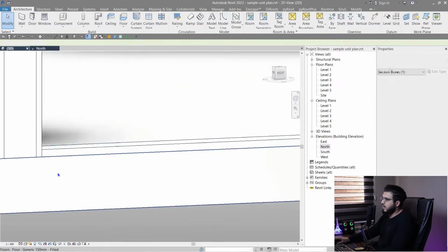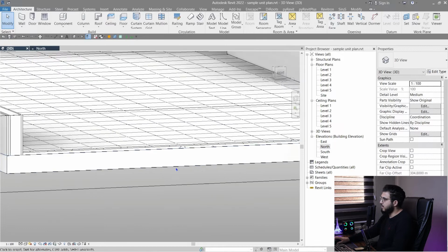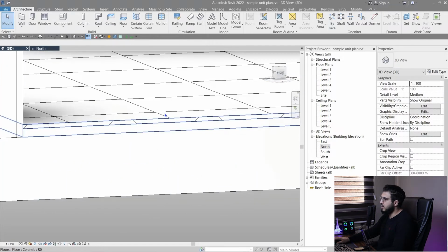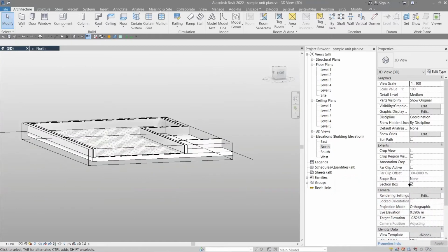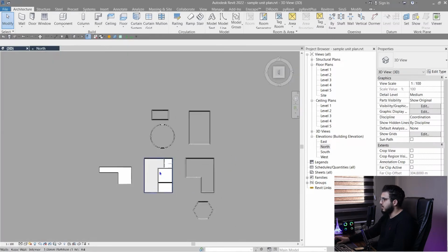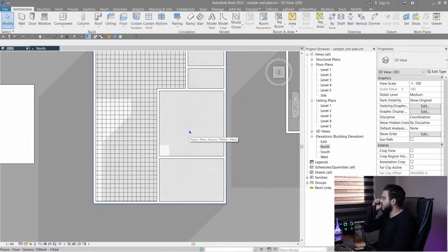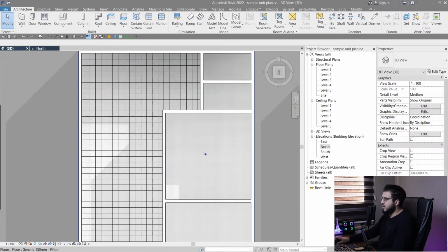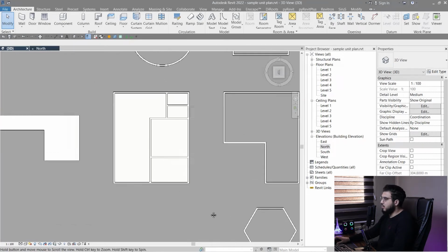As you can see right now, we have our walls in here, our main floor and a structural floor in here, and then we have our finish floors in here, and we need to create finish floors or finish layers for each room separately. For example, if you want to use parquets in here, you need to create a second type of floor for your parquets and use it in here. So that's the way that you can create floors in your buildings.